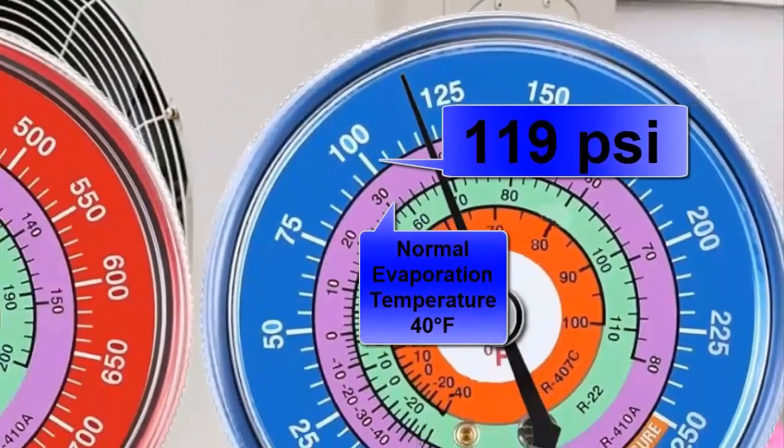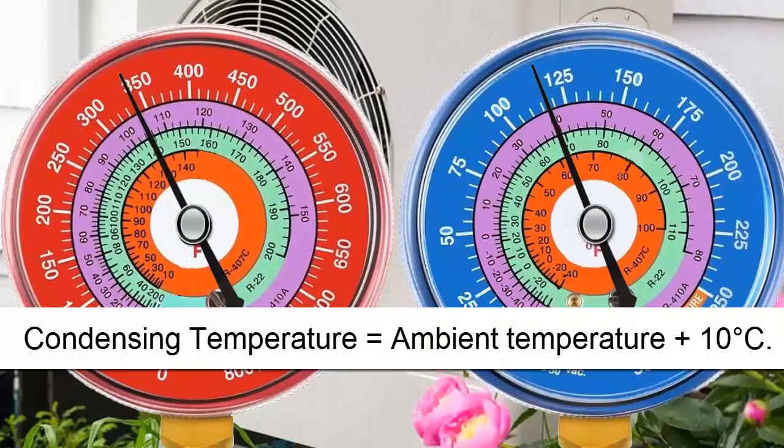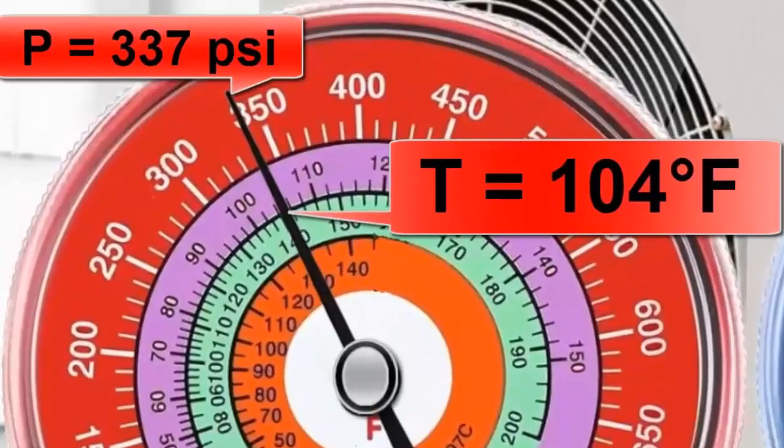C. On the high side, to estimate the normal pressure, we take the ambient temperature and add about 10 degrees Celsius, 18 degrees Fahrenheit. So for an ambient temperature of 30 degrees Celsius, adding 10 degrees Celsius gives a condensation temperature of 40 degrees Celsius, about 104 degrees Fahrenheit, which corresponds to a high pressure of approximately 337 psi.